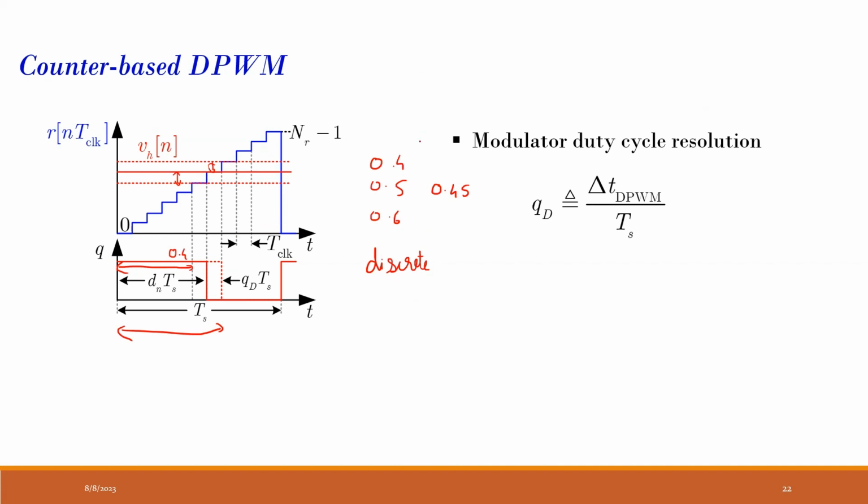Let me explain a little more easily. You have a scale. This is my scale. Let us assume it is 0 to 1 centimeter. It will have some 10 possible divisions, so one division corresponds to 0.1 centimeter. So those are the only values. The minimum value which you can measure using that scale is only 0.1 centimeter.